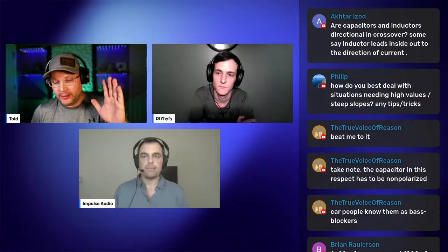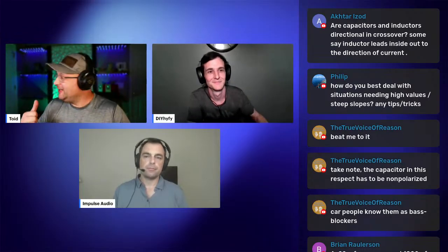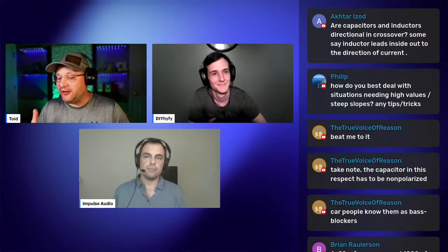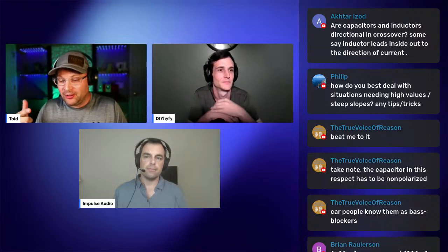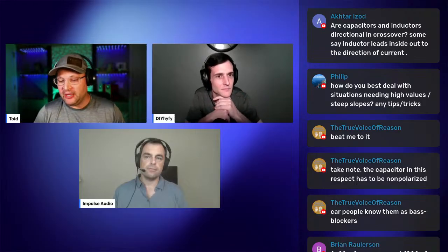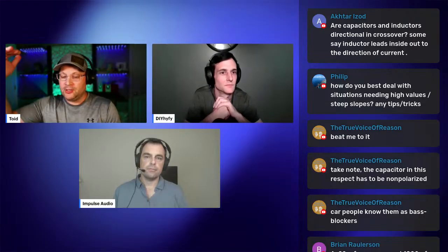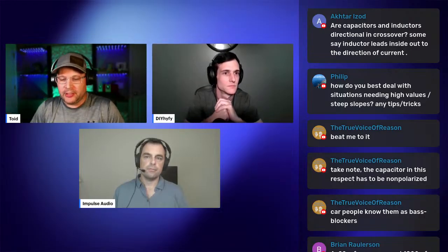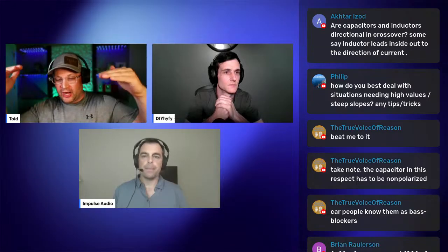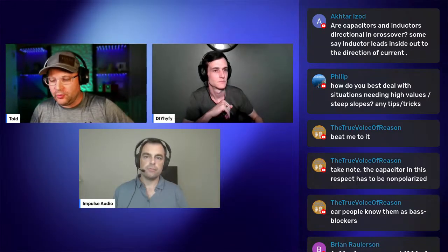So basically a capacitor's whole purpose is to stop the bass from getting to the tweeter. Now, a resistor doesn't care if it's high or low frequency. A resistor resists everything. And so that's why we usually use that for one of two things, either taking care of impedance or lowering your actual driver level matching, so bringing your tweeter level down to your woofer.